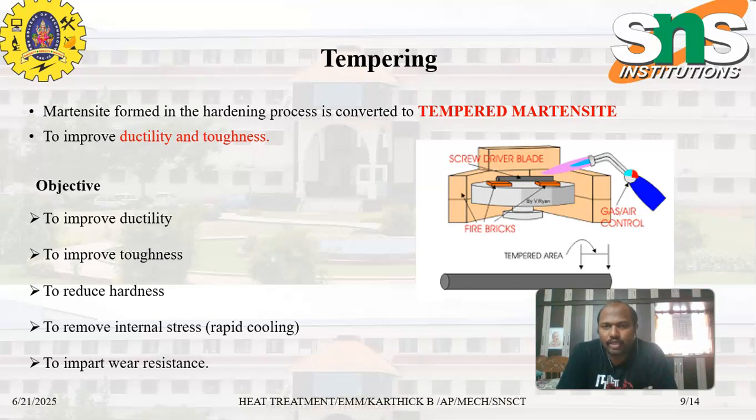In the previous video, we have seen two types of heat treatment. One is hardening, another one is normalizing. As a refresher, in normalizing, as usual, heating, holding and cooling takes place in normal still air. In the hardening process, again it's heating, holding and cooling, but the cooling takes place very rapidly, which means that we